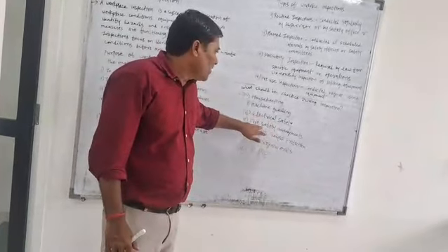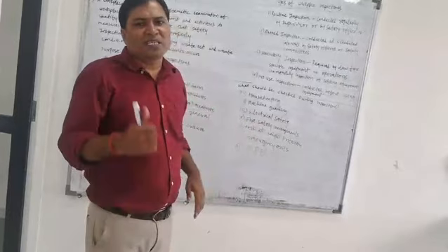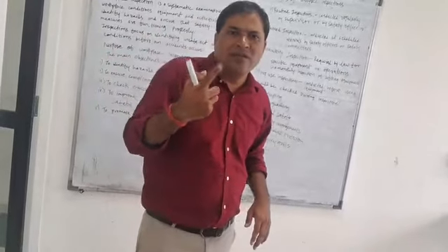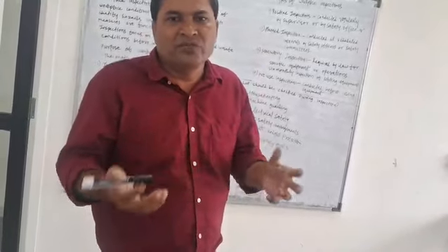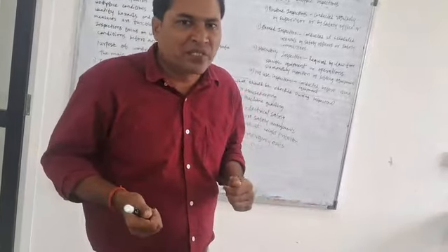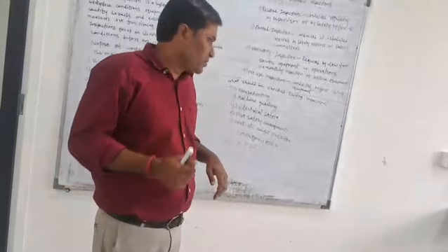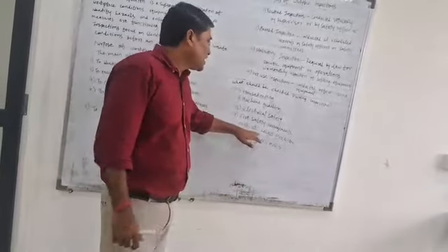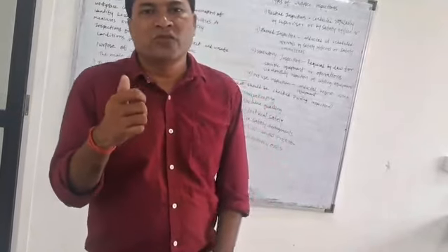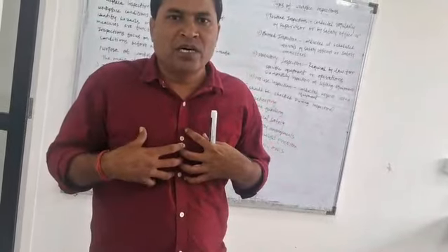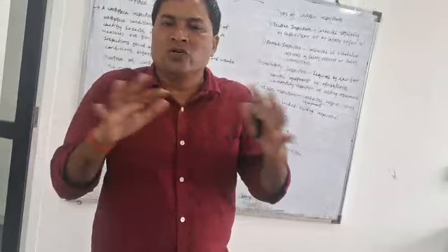Then electrical safety, check all the wires, all types of wire which are connected with the same machine. Okay. Fire safety arrangements like fire extinguishers, fire blankets, CO2 trolley systems, CO2 extinguishers or DCP systems. Okay, sprinkler systems, that kind of systems. Work at height protection, for protection at height you have to go with the proper harness with ladder or scaffold.